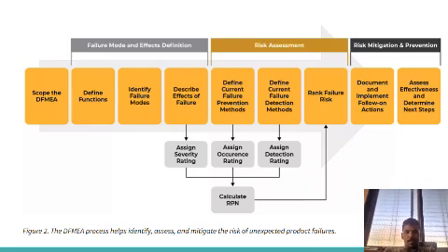Failure mode and effect definitions, risk assessment, risk mitigation and prevention. Scope the DFMEA, define function, identify failure mode, describe effect of failure, define current failure prevention method, define current failure detection method, rank failure risks.